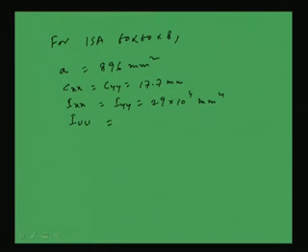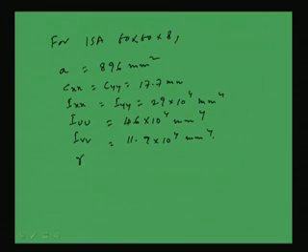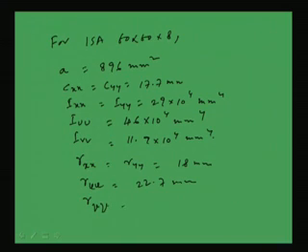So, IUU, that is moment of inertia about major axis, will be 46 into 10 to the 4 and IVV will be equal to 11.9 into 10 to the 4. Similarly, I can find out other properties like RXX, the radius of gyration in x direction and in y direction, is 18 millimeter, and RUU will be 22.7 millimeter and RVV is equal to 11.5 millimeter. So, these are the required properties which will be helpful for calculating the equivalent sectional properties of the member.